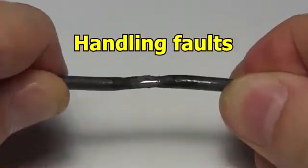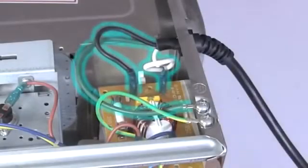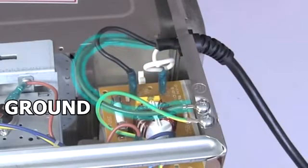That's in case you have a break in the insulation covering a wire somewhere. That break can cause a fault, such as in this microwave oven. 3 wires enter the microwave oven. Those 3 wires are connected to the 3 prongs of the plug, hot, neutral, and ground. As we said, the electricity flows through the hot and neutral wires. The 3rd wire is the ground wire. The ground wire is connected to the metal case, and normally no electricity flows through it.